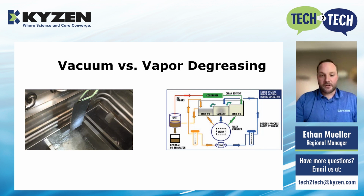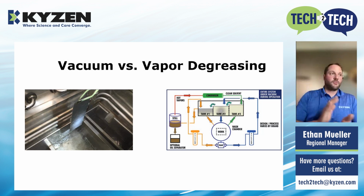And the solvents that are used in these tend to be volatile, low surface tension, so they get in the part, they come back out of the part, they evaporate away very quickly. The vacuum process is a little bit different. You put the parts in a chamber, pull a vacuum over that chamber, you introduce the solvent so there's no gas in there. The solvent does have a relatively low surface tension, not as much as the solvents that are used in open top vapor degreasers.